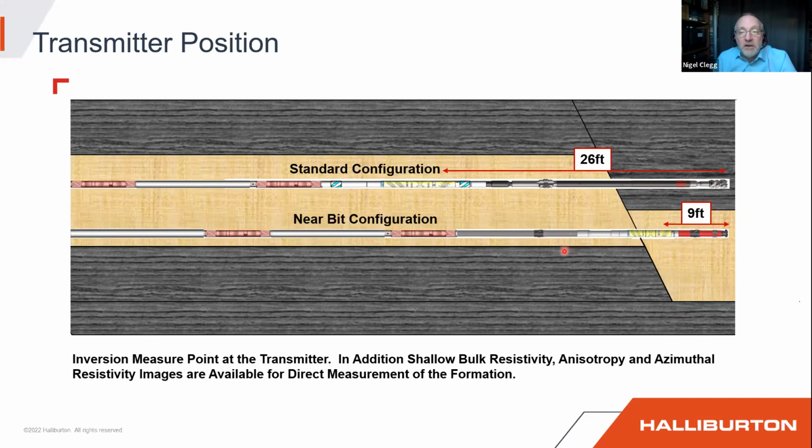purely so that you can identify those changes and make good geosteering decisions. When we're in a well drilling these, we can only make changes of a few degrees at a time. You can't put huge big bends in your well as you're steering. So you need to make those decisions early to be able to make sure that you can actually hit the targets that you're aiming to hit.